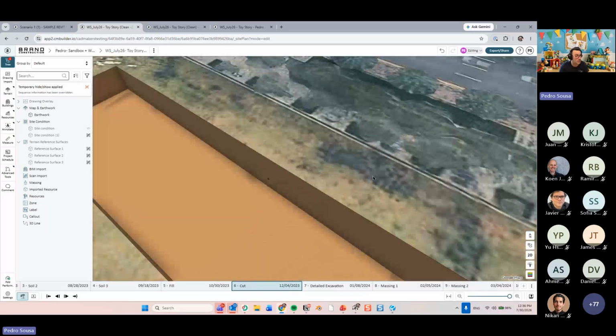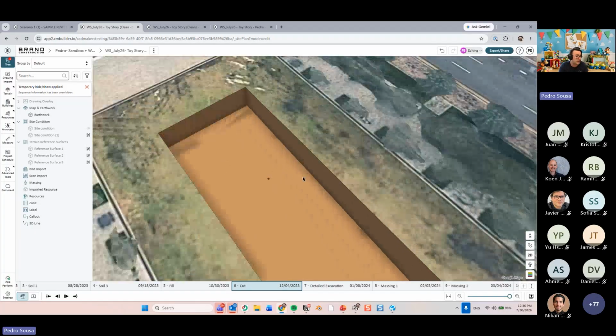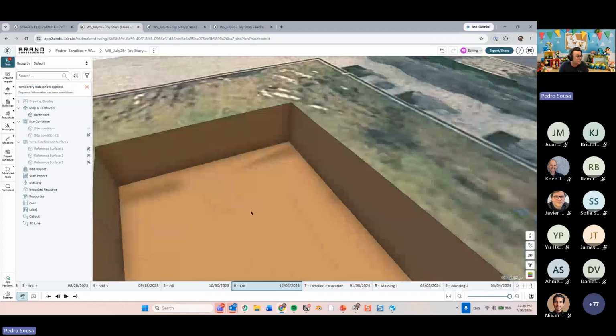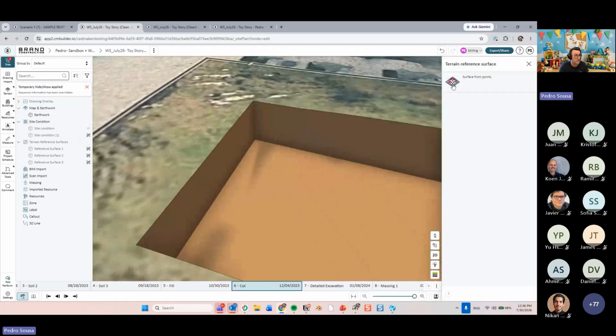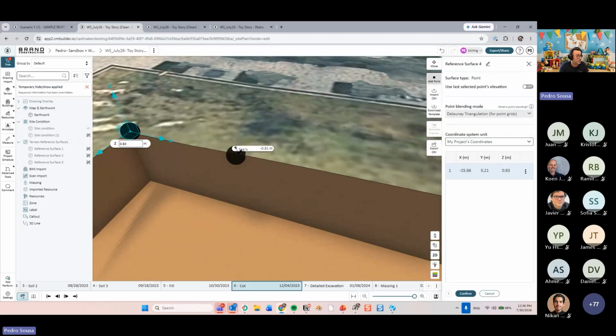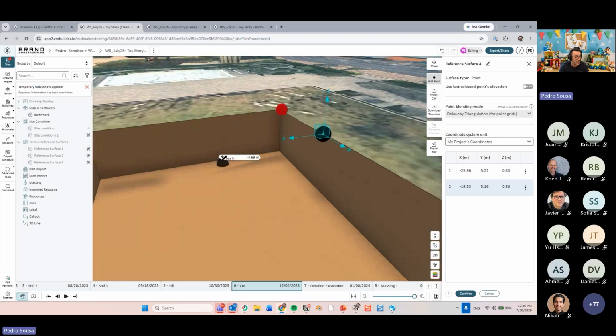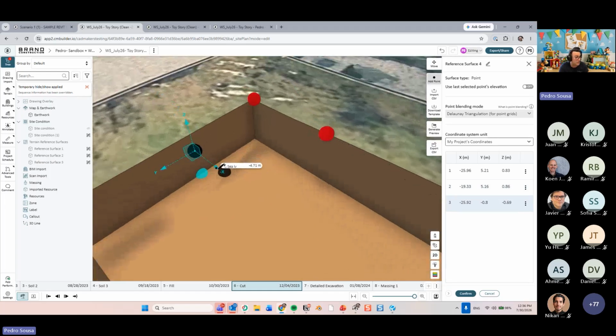And let's say that I wanted to create a sloped ramp coming this way, right? Starting over here and then curving inside. So I will go ahead, same idea, create a reference surface, put in points, and I say, okay, my start of my ramp is going to be over here. And then that ramp should be maybe halfway over here,